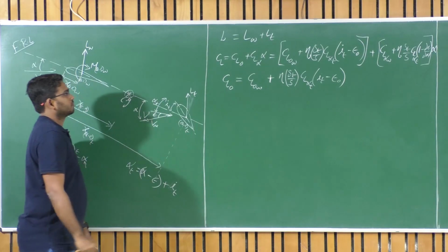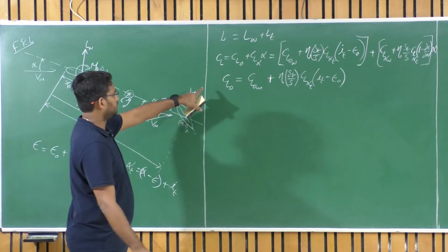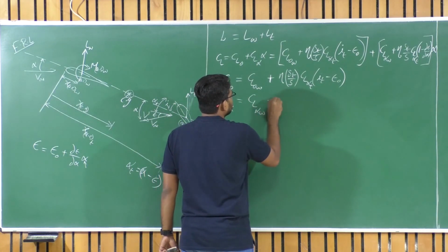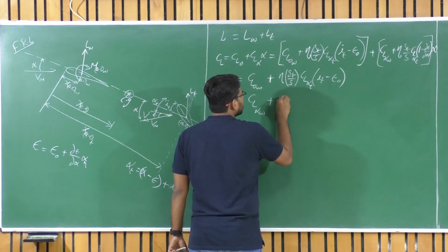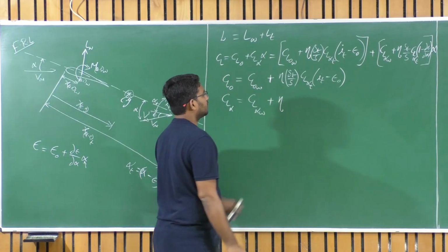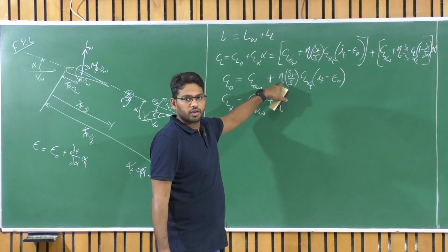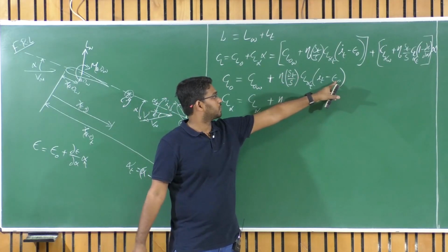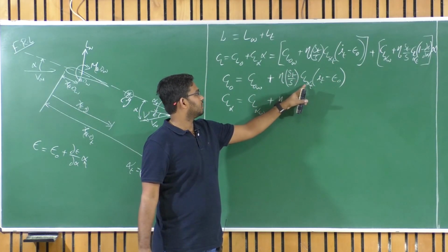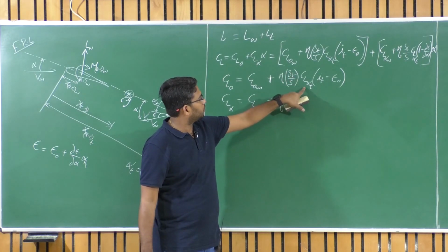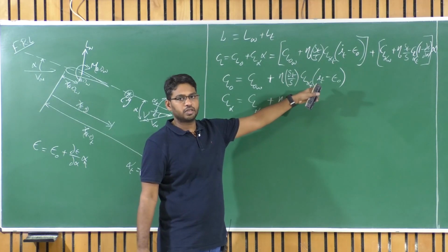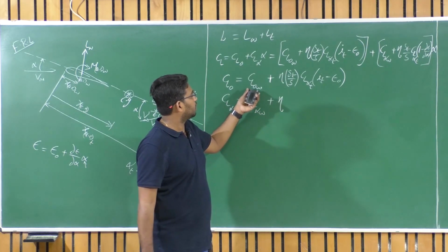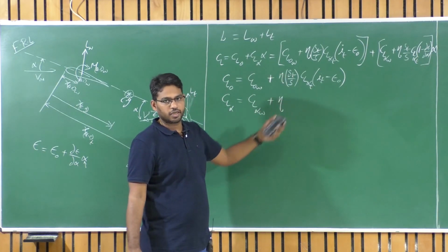Okay. So this is the CL naught of the aircraft, and CL alpha of the aircraft: the contribution comes from CL alpha of wing straight away, and this modification. Eta of the horizontal tail is nothing but half rho v prime square upon half rho v square, that can be 1, right, when there is no downwash, that means epsilon can be 0. So if you have equal wings, same wing as wing and tail, what you have is just CL alpha times i of t. If i of t is also 0, let us say, then what you will have is CL naught of wing plus CL naught of tail directly.